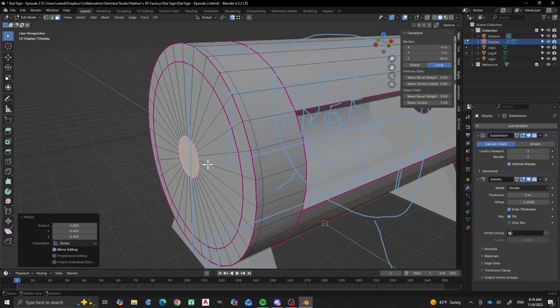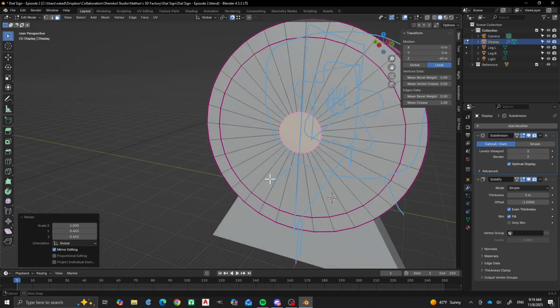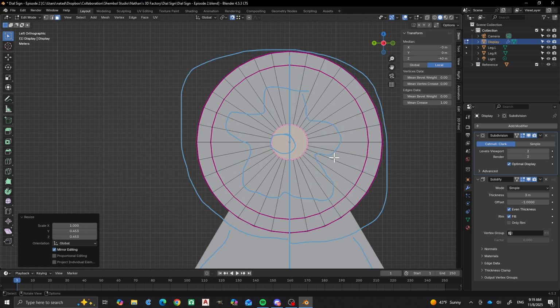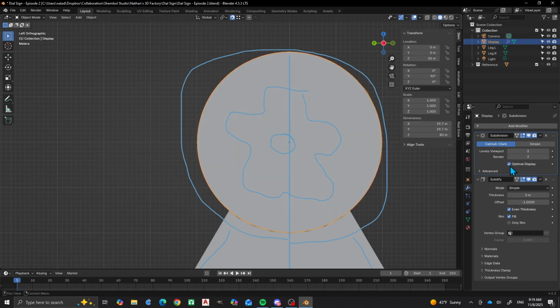And then I'm going to do the grid fill here because I'm satisfied with this. Actually, I shouldn't say that yet. I'll do that after I've applied the modifier here, okay? I want to keep this as an n-gon. So next thing I want to do is solidify. We're going to apply that modifier.